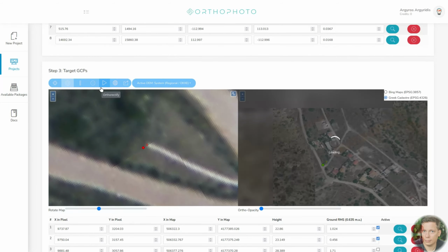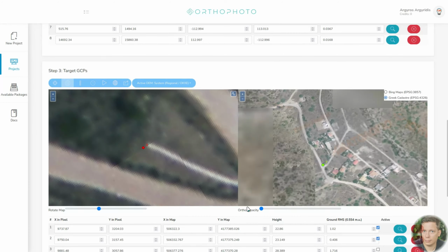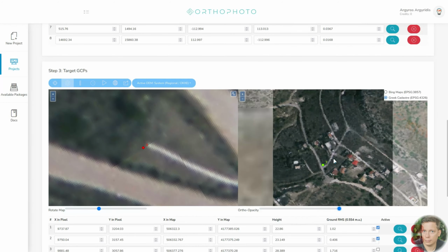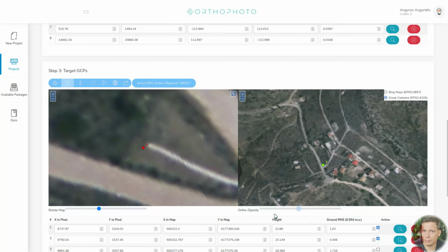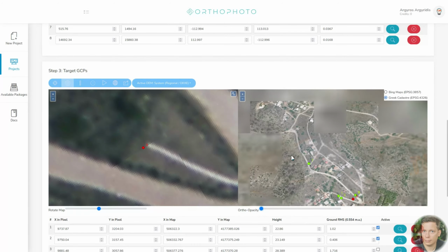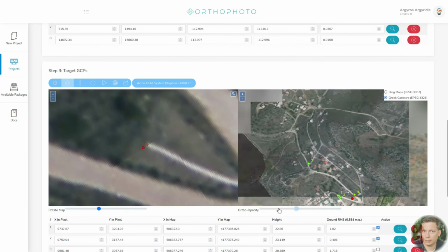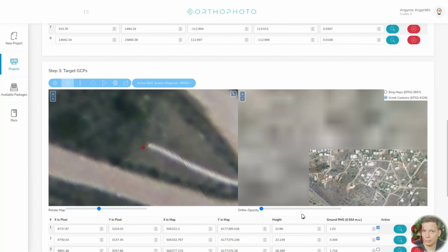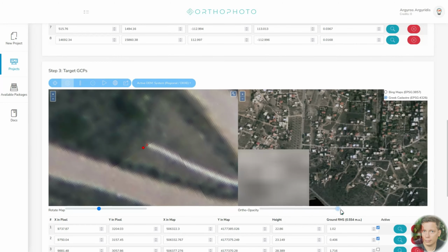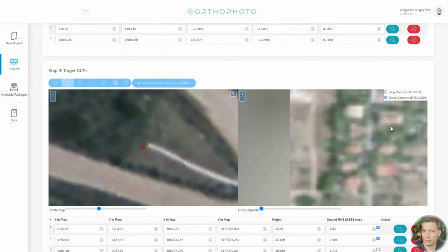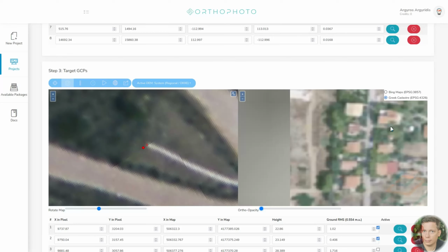Normally, targeting GCPs requires a good distribution over the entire surface of the image. However, we already achieved a very good result even by using very few points and without utilizing very precise GCPs. Our horizontal information was acquired from a WMS and vertical information from a DTM model generated through automatic matching. So there is plenty of room for improvement here.